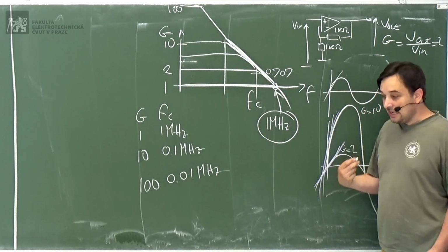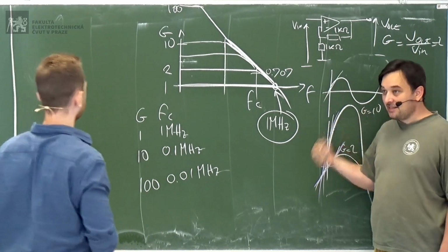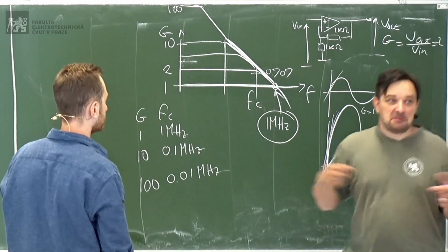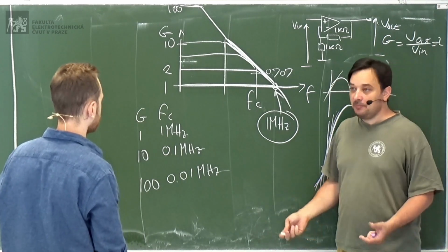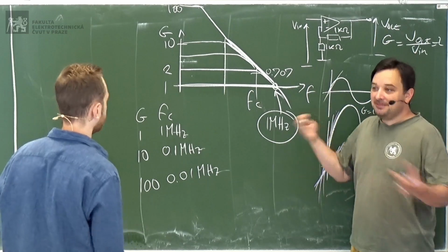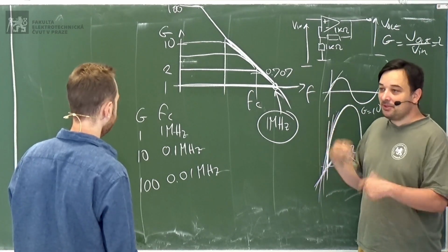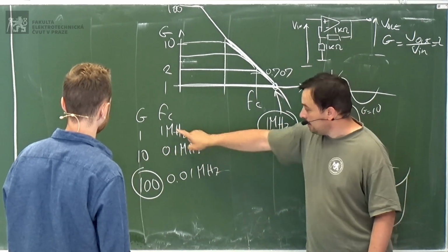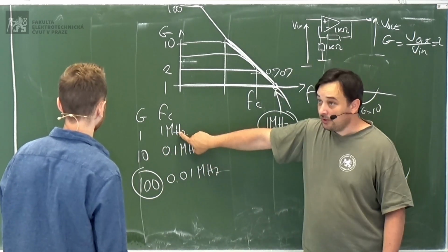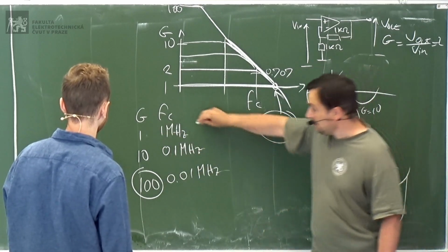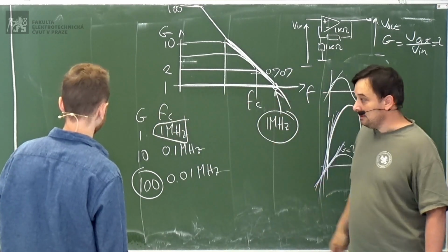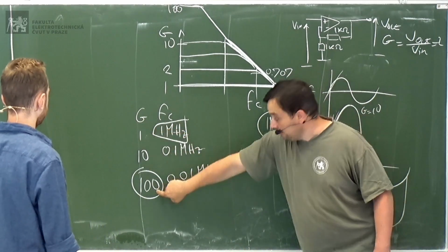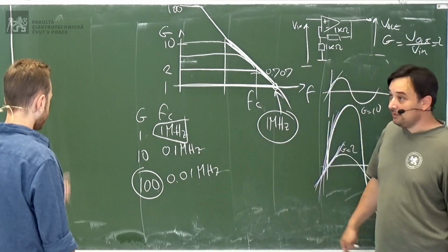So when you make your design, you're saying, okay, which is the maximum gain I want in my project? I don't know, you have to amplify your signal by 100 times, because the sensor needs to see something. The design of the project requires you to amplify 100 times. Okay, cool, 100 times. What does it mean? I have to take the cutoff frequency with the gain 1, which is data that you get from the data sheet. This is for the gain 1. For a gain of 100, you have to divide and you get...